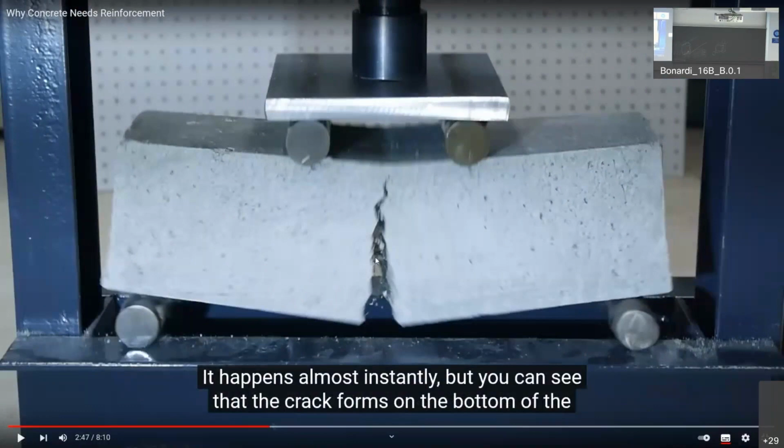So when does it fail? It fails at the bottom. Okay? So a crack starts at the bottom and develops upward. Because I showed you that when a crack occurs, the element survives until there is the possibility to counteract compression with tension.